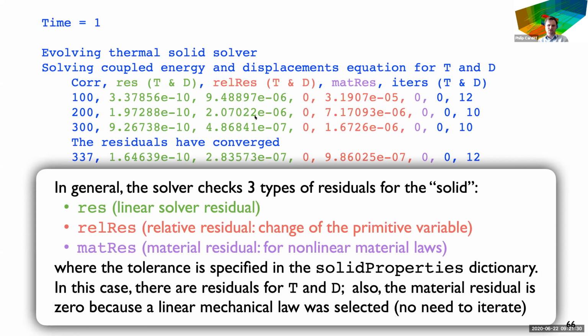So why do I have 2 residuals? Well, a residual is just a measure of how much the solution is changing while you're iterating. But it's really critical how you pick the normalization factor, whether that would be correct or not. And it seems that there isn't really a robust way of doing that for every type of test case. In some test cases, just the way the OpenFOAM initial residual is normalized, it seems like a case is not converged when it is.